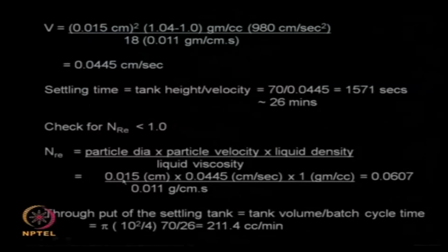But in reality the solids may take slightly more time to reach the terminal settling velocity. So you may have to keep the slurry inside the cylindrical tank for much longer than 26 minutes to achieve a real complete separation.